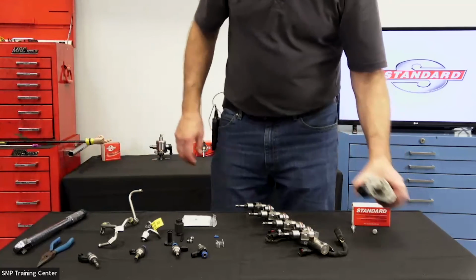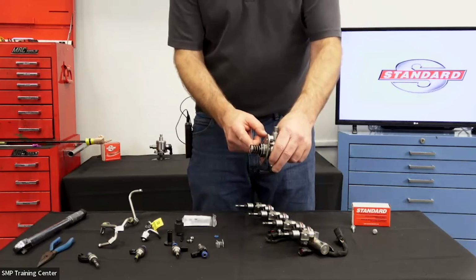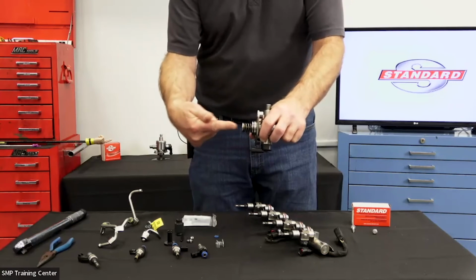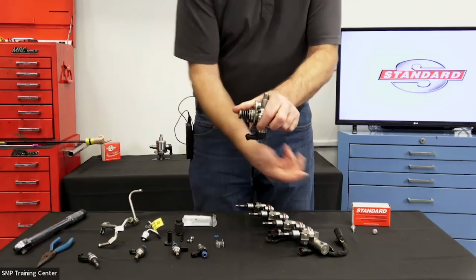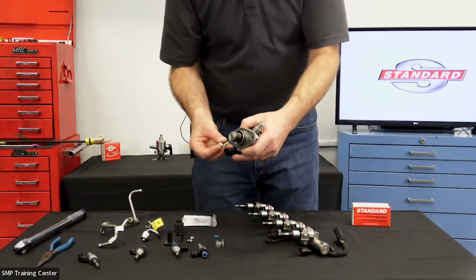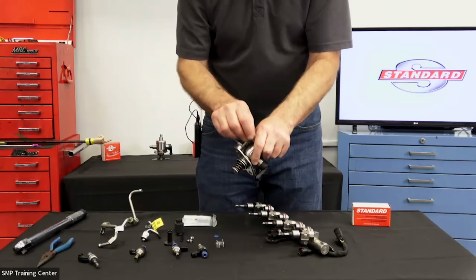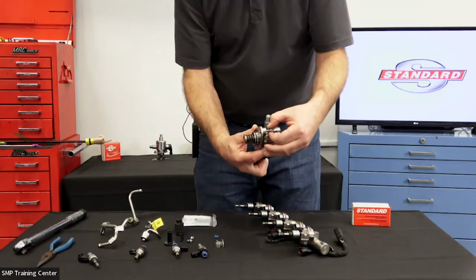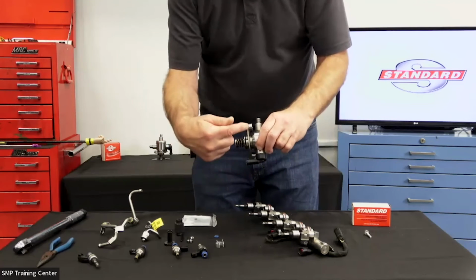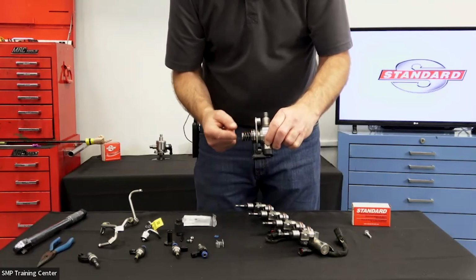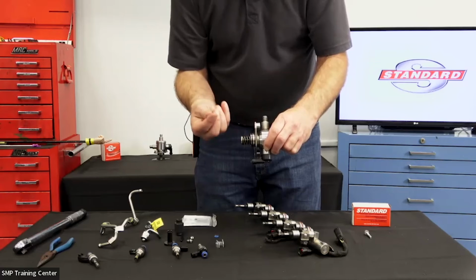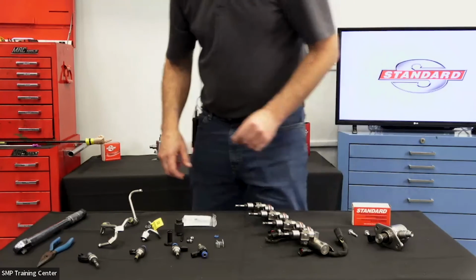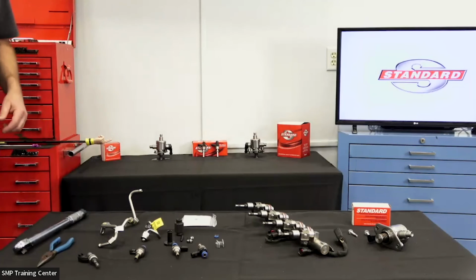Now here's this high pressure pump you see here, and there is a very, very powerful spring. So if we're on a high point on a cam lobe, we would be battling that spring to install it. And in fact, of course, we have these mounting bolts right here that we would probably be using to pull that pump into place. Well, in that case, again, if we're on a high point on a lobe, we could actually warp or damage the housing of the pump. We could actually pull the threads out of the aluminum cylinder head that we're bolting this thing to. So that's going to be a concern with regard to the installation of a high pressure pump.